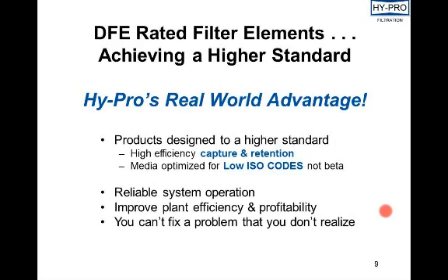Also, we use the DFE test to optimize our medias to achieve the lowest ISO code possible with not as much focus on a beta ratio. What matters most to customers is how clean is my oil and how long will my filters last. So that's our goal, to achieve the best ISO code while balancing long filter element life and high efficiency.